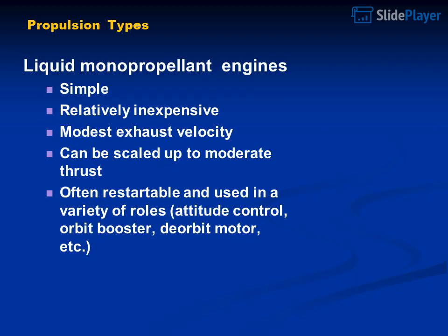Liquid monopropellant engines. Simple. Relatively inexpensive. Modest exhaust velocity. Can be scaled up to moderate thrust. Often restartable and used in a variety of roles: attitude control, orbit booster, deorbit motor, etc.